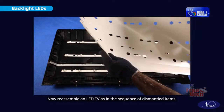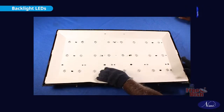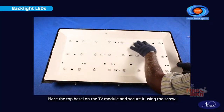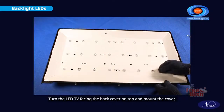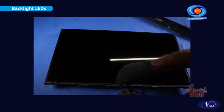Now reassemble an LED TV in the sequence of dismantled items. Place the top bezel on the TV module and secure it using the screw. Turn the LED TV facing the back cover on top and mount the cover, which was removed earlier, with screws.